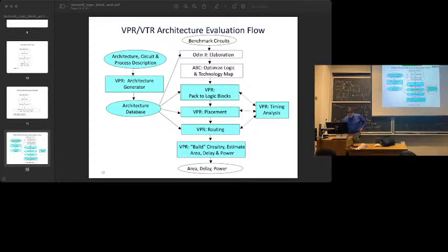Okay, and then when those are done, if we were running Quartus, Quartus is similar to this; you change the names of which tools it is, but it goes through the same basic phases. Quartus is going to produce a bit stream here, so it'll go to a programmer. It will also tell you what the delay is, and it'll tell you what the power is.